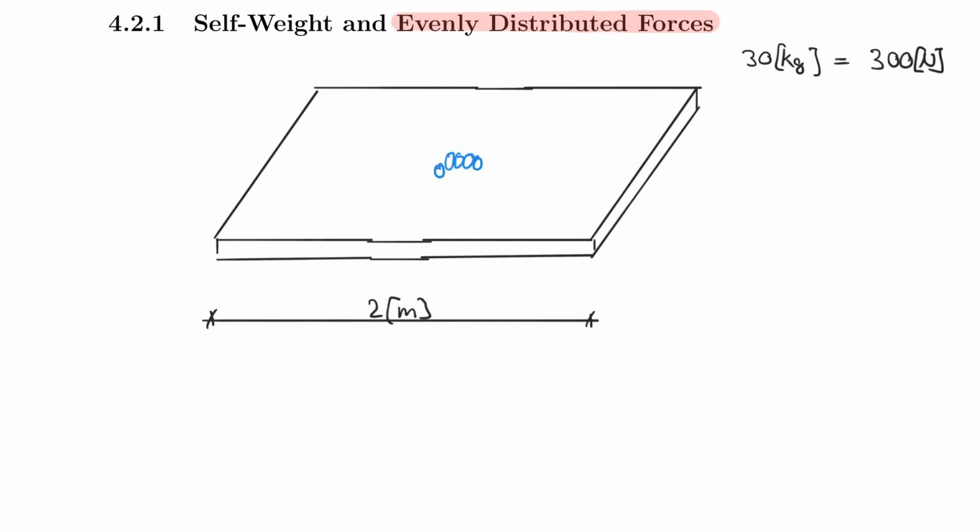So let's do that. Now, why did you do that is the big question. You intuitively knew that the table is actually a rectangle and the force is evenly distributed. You knew that the force is acting in the center of gravity. You may not know it as the center of gravity, but if you draw the diagonal through a rectangle, you will know that the force is actually acting right there. And what you have done, you have applied engineering mechanics concepts, because everything here to the right of the force balances everything to the left of this force, right?